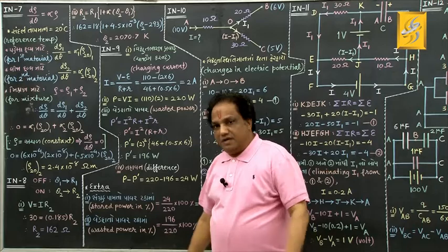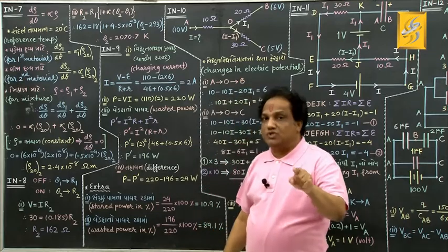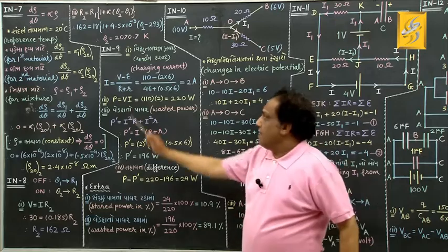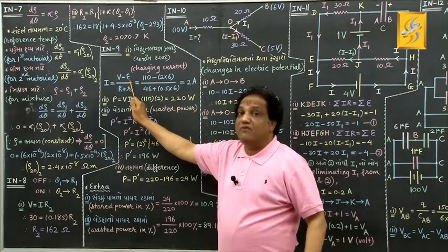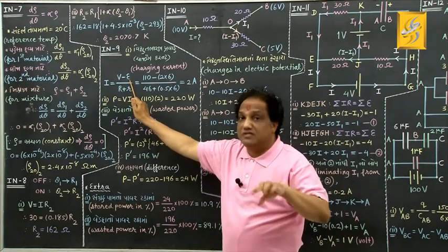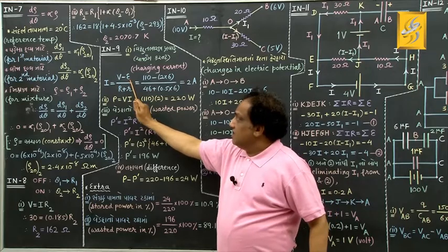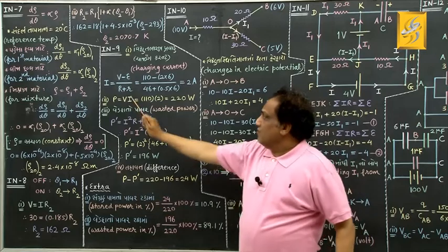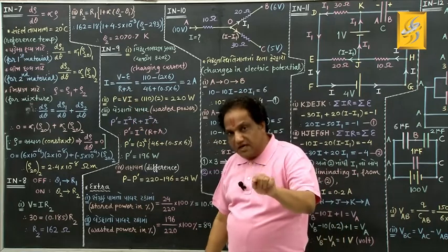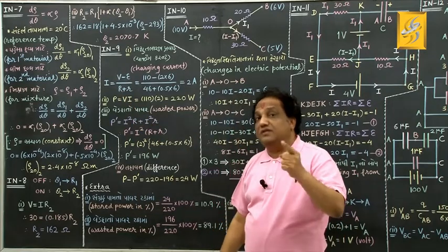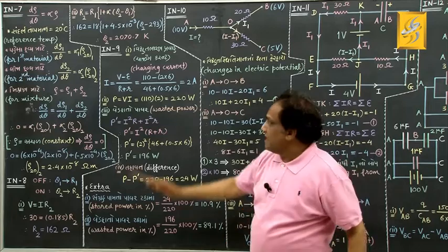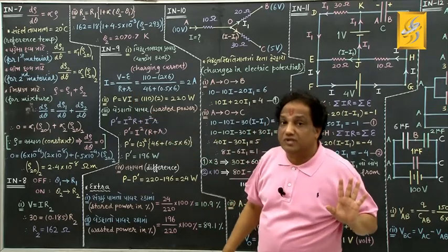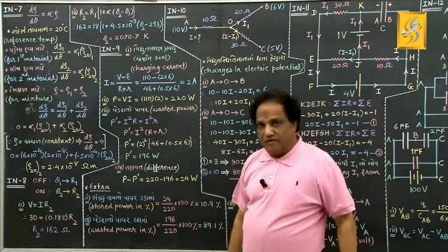What is this capital V? It is the terminal voltage of the DC source connected for the process of charging of a given lead storage cell. Correct? And that terminal voltage is higher than the EMF of the lead storage cell, which is to be charged up. Okay? This is the effective EMF of the lead storage cell, which is to be charged up. What is capital R? Resistance connected in the external part of the circuit in series with the lead storage cell. And this small r is the effective internal resistance of the given lead storage cell. Got it? Come on, put up the values.